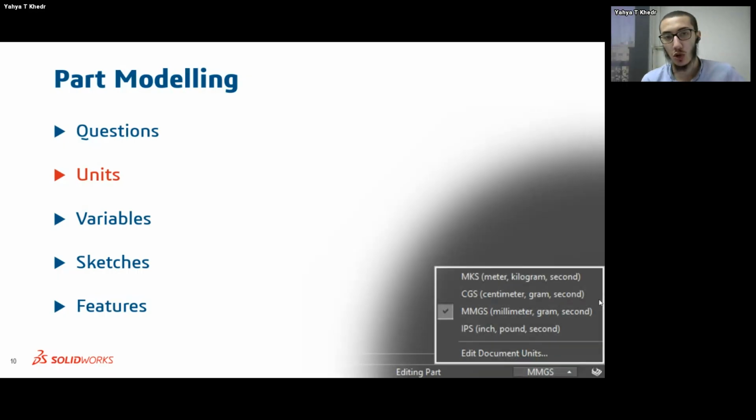Some of us will just start SOLIDWORKS, create a new design, and just start sketching and creating the model. That's not wrong, but this is something that I've personally been a victim of, which is to forget to set the correct units. Okay, so in some questions it might tell you to create it in inches, in other questions it might ask you to do it in centimeters or millimeters, and so on. So it's really important before you start creating your very first sketch to make sure that you've got the units correct, because the thing here is, if you create the sketch, let's say for example you create a square, and that square is 10 millimeters by 10 millimeters.